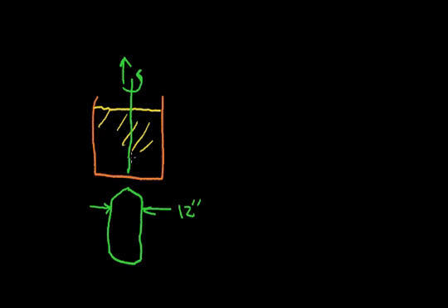Now, I should mention that a small amount of impurity will be added to this silicon molten mixture. For example, if you want to have P-type silicon, you introduce a small amount of boron. If you want N-type silicon, perhaps you'll introduce a little bit of phosphorus. Now, once this ingot is created, it can be sliced into very thin layers. It's like slicing up a sausage. This is like a big sausage. And these little slices are like slices of bologna.